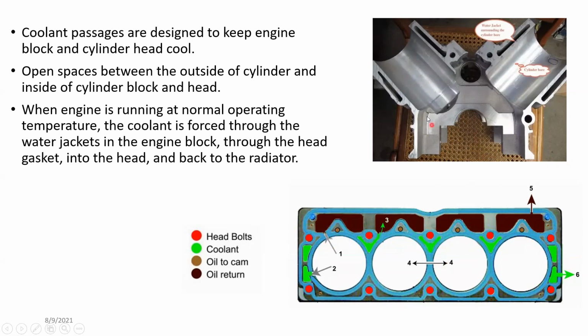So the coolant flows from the bottom, goes upwards, then comes through the cylinder head and moves back to the radiator.